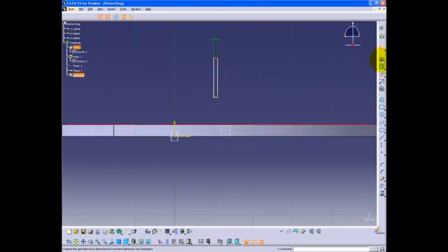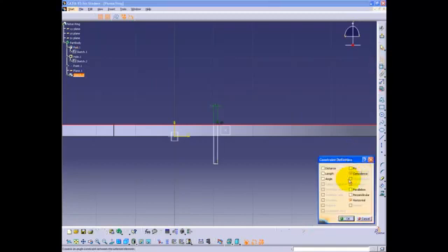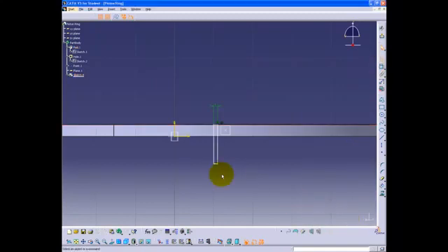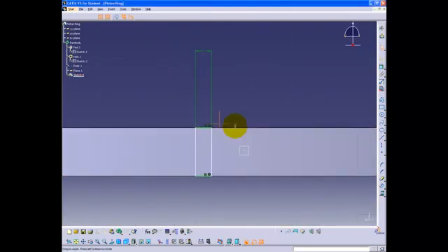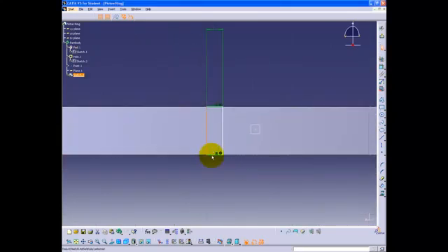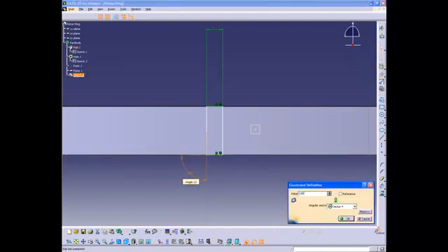The top and bottom of the rectangle are constrained to the ring by selecting Coincidence in the Constraints Defined in Dialog box button. Selecting one of the side edges and the bottom edge while holding the Ctrl key, the angle is constrained as 135 degrees.